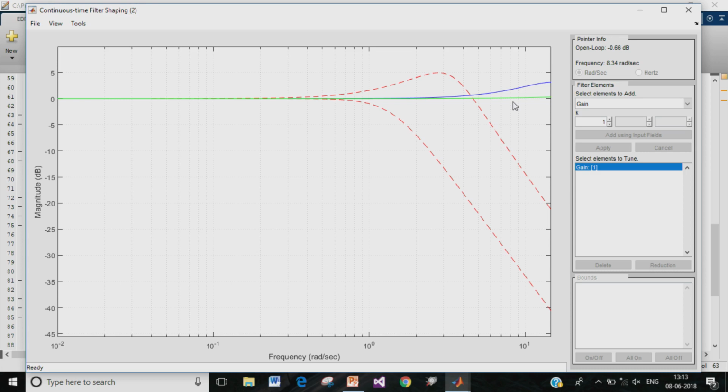However, while the restriction of the variation in the transmission function has been successfully achieved by the feedback controller, the nominal transmission function has to be designed, and this is done by using the pre-filter. We can choose the pre-filter to have a real pole, for instance, placed at 3 radians per second.